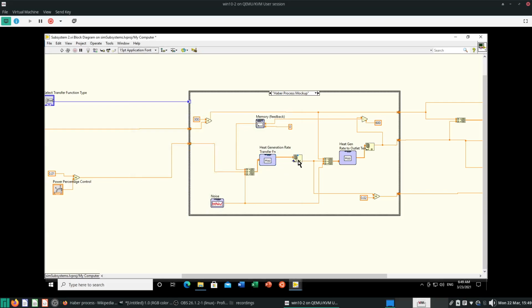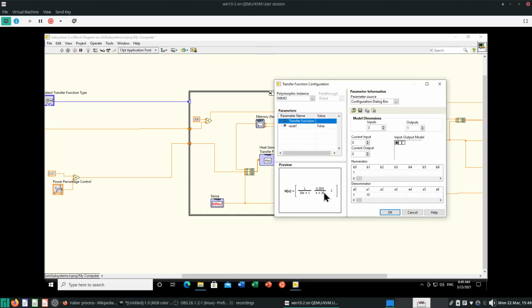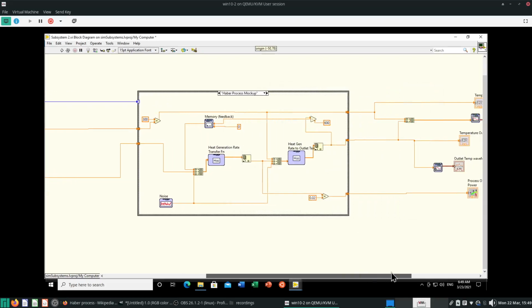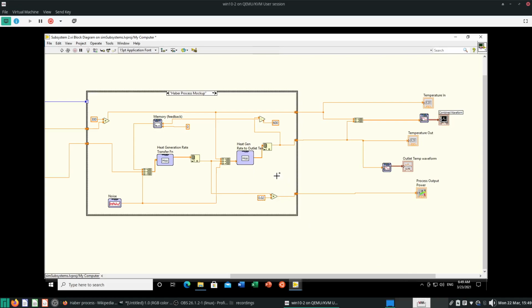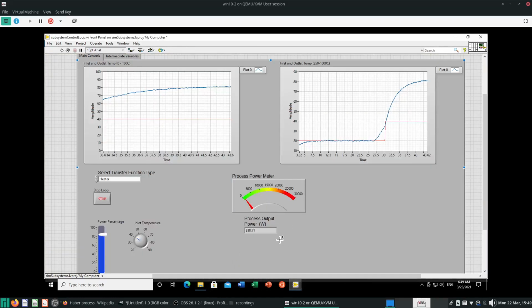Okay, so it will pump out a so-called reaction heat output rate in some arbitrary units. I didn't care about units here. And then I just pump it into this transfer function here, which takes 0.005 times the heater output, the heat supplied to this reactor, and then it gives it some process time. Nothing too fancy. All right, so to get this heater power, I just did this very lazy workaround. I just took whatever random number here and scaled it down arbitrarily just to fit the scales over here. That's what I did. So overall, that's how this whole system works.